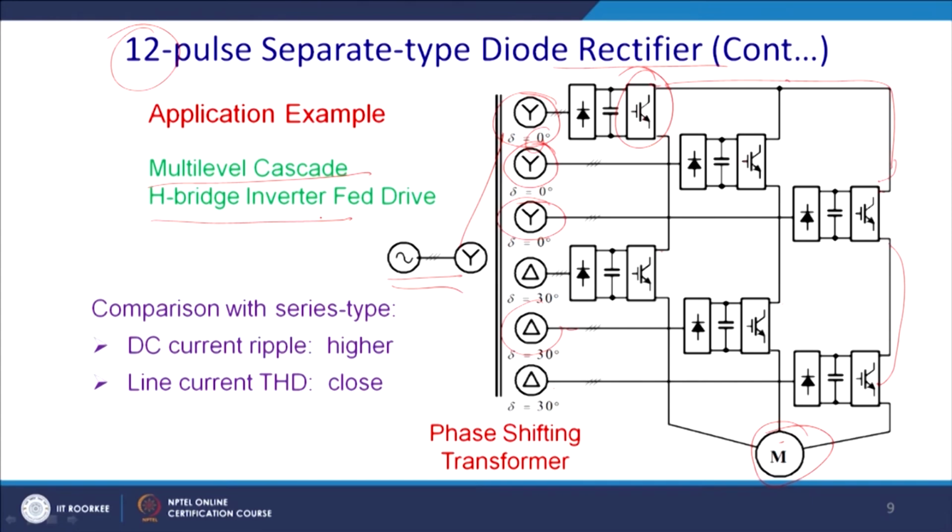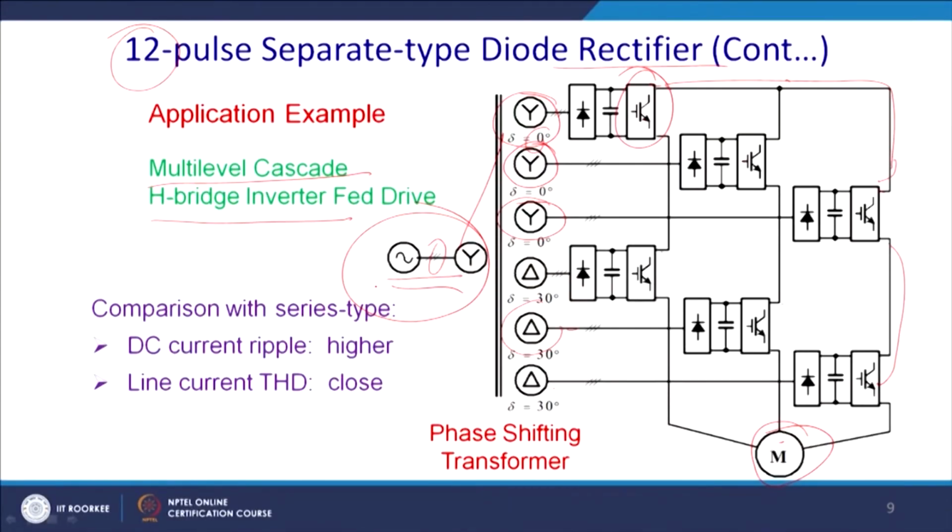The 24 pulse version has got the Siemens patent, and for the sake of simplicity, I am showing the 12 pulse version of it, and it has huge advantages. See the advantages. Ultimately, you get a very good power factor as well as THD.